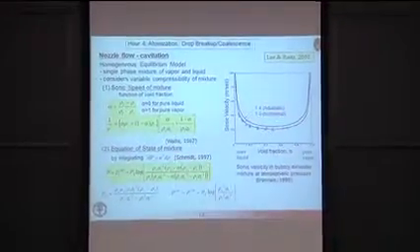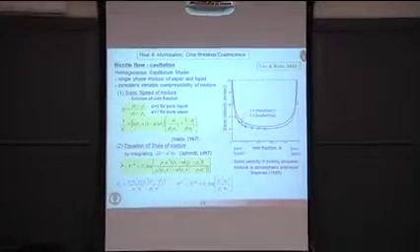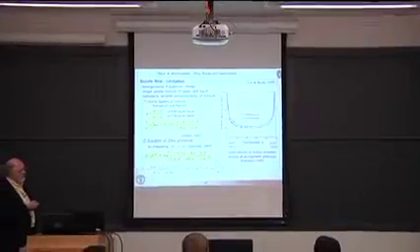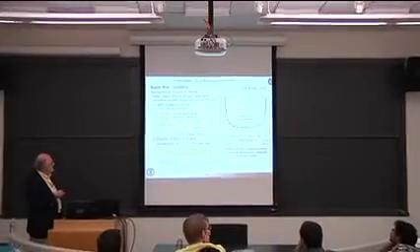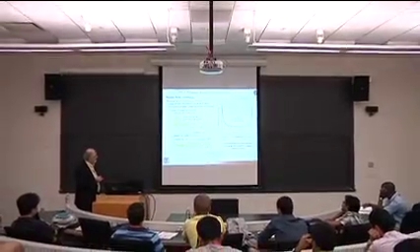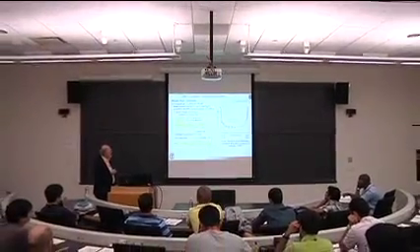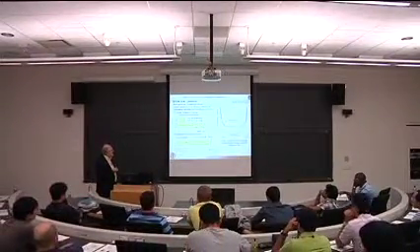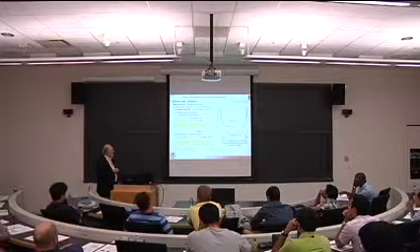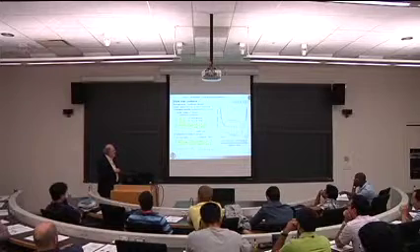So you can define this parameter alpha here, which is essentially a void fraction, which is 0 if you have pure liquid, and it's 1 if you have pure vapor. And from this equation, which comes from Wallis' classic equation, you can predict the sound speed in terms of the sound speeds of the vapor and the liquid.